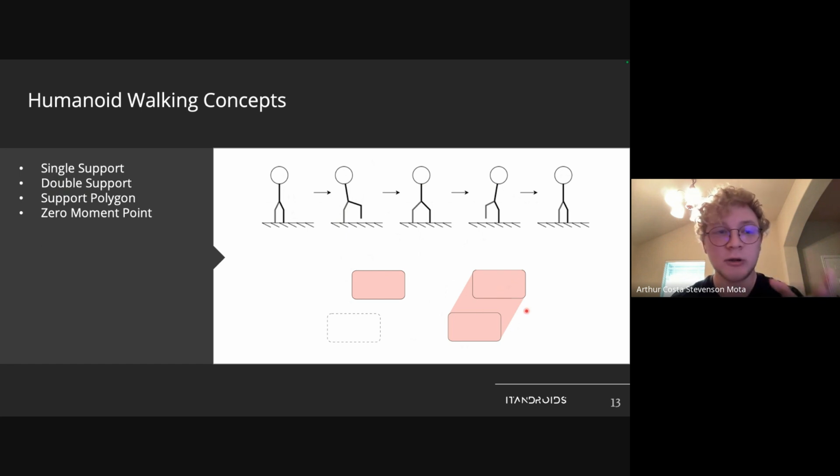And the support polygon is important for the zero moment point stability criterion, which I referred to earlier. The zero moment point is the point in the foot where the foot-floor reactions are being applied. If it is inside the support polygon, the robot will be stable, so it will not topple over. As I said before, it is a very important stability criterion, which is very widely used in academia today.